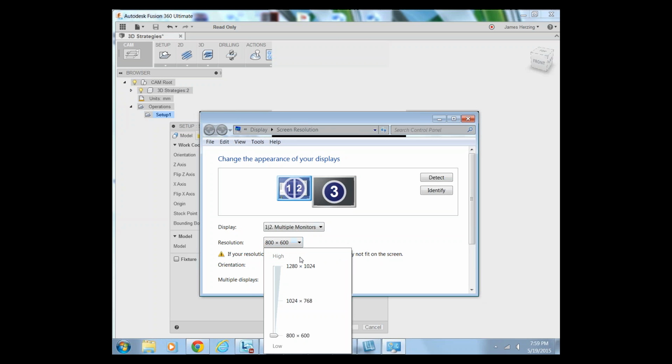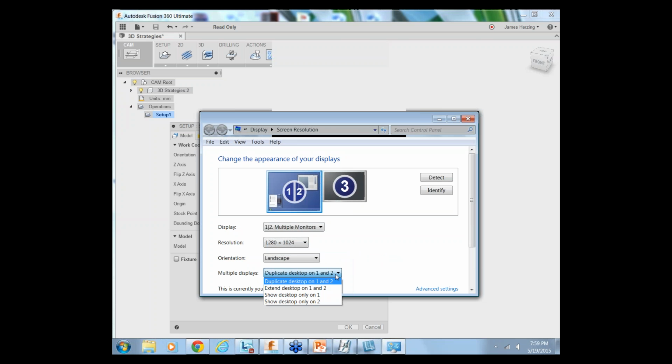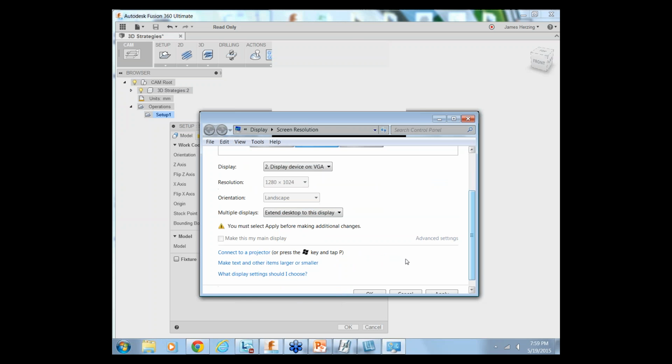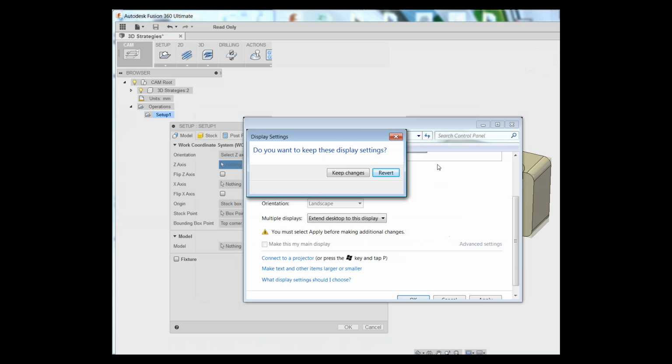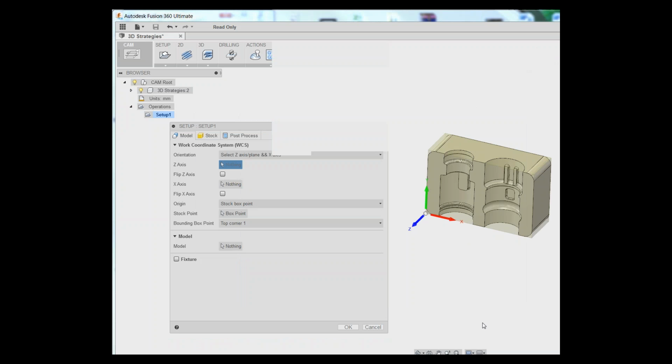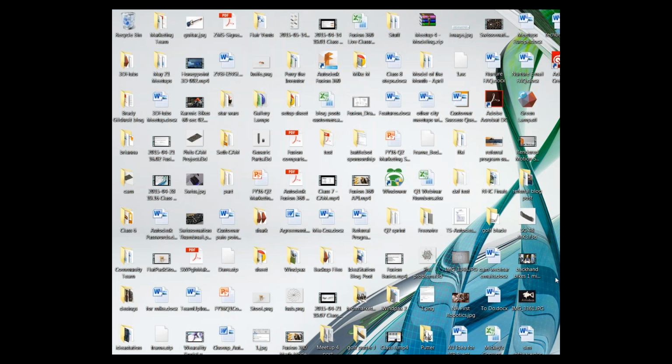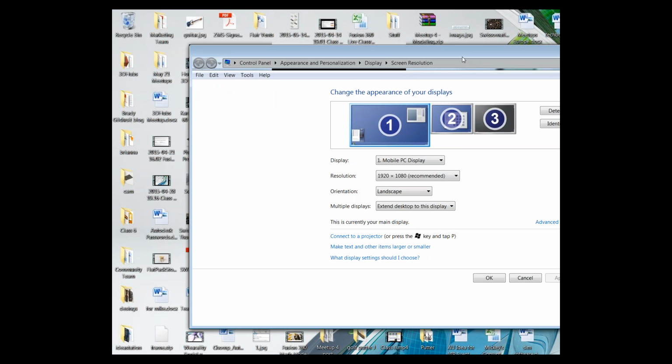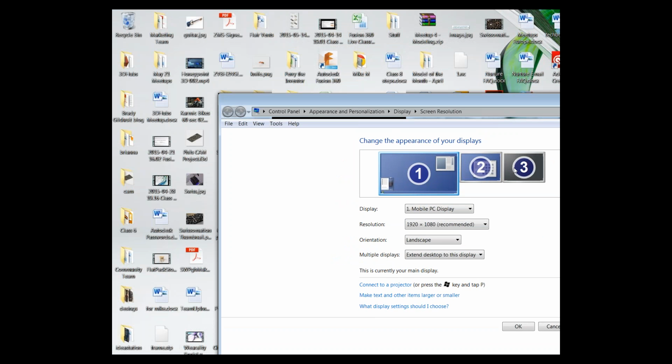If you're doing 3D machining, you'll be moving in X, Y, Z axis simultaneously, but if you still have an undercut or another edge or surface that the mill cannot get to, you do have to reorient the part. Now, 2.5D is typically moving in X or Y, and then a Z change. Or sometimes it's a Z change and then a Y change. You could do an X, Y wrap with a 2.5D, where you could do it with the fourth axis. Fusion doesn't have fourth axis code yet, so if you actually need fourth axis work, the only software package in the shop that can do it is InventorCam or VCAR.